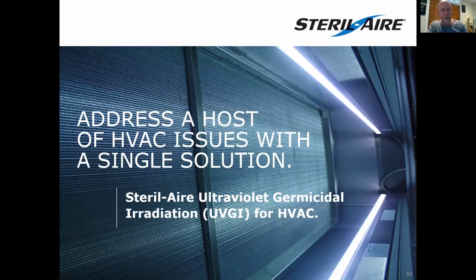So the higher the quartz glass you use, the more UVC output you can get from it. It's also to do with the blend of gases within the lamp, and it's also to do with the electrodes. So the electrodes are made of precious metals, and it's the quality and the design of these metals that also produce the high output. So that's one part of it. The other part, and it's because I said right at the start, this is a system engineered product. The lamp and the power supply are system engineered to produce that high output.